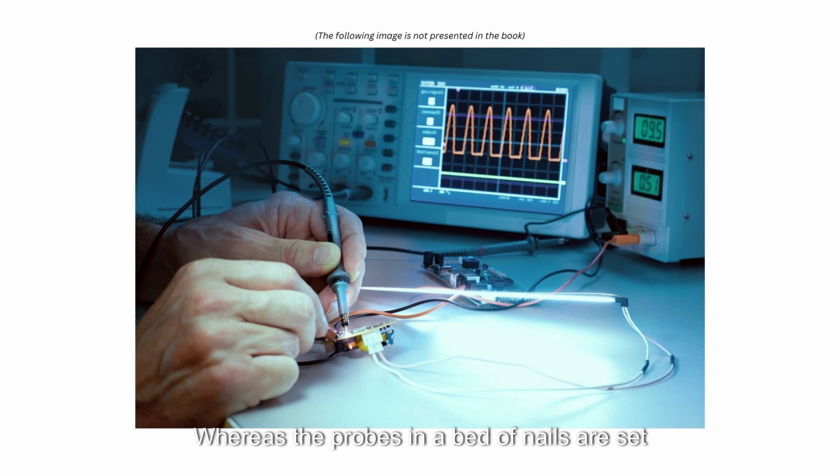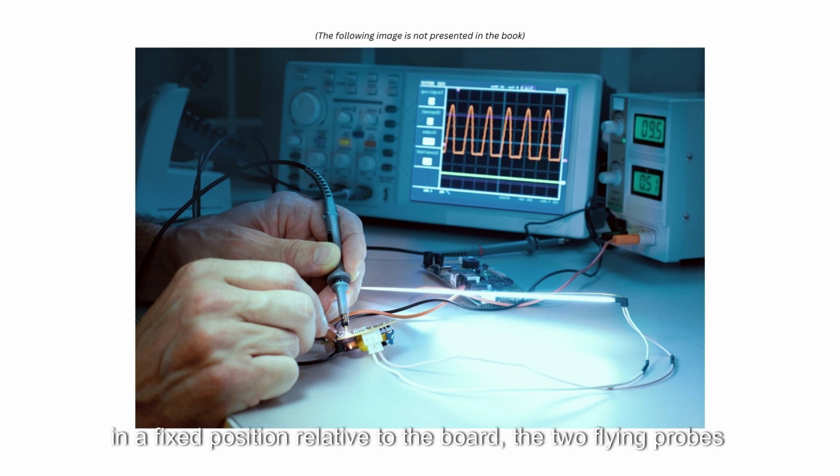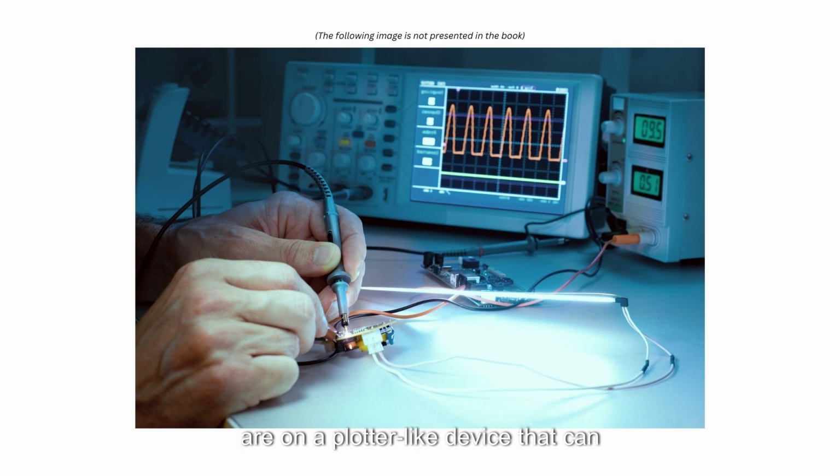Whereas the probes in a bed of nails are set in a fixed position relative to the board, the two flying probes are on a plotter-like device that can move in any X, Y, and Z direction. It is programmed using the Gerber, pick and place, and test point files. These file types will be discussed in detail in later chapters. Devices with lead spacing down to 0.635 mm, 25 mil, can be tested with flying test probes. Spacing of 1.27 mm, 50 mil, is almost the norm for today's device pin spacing.